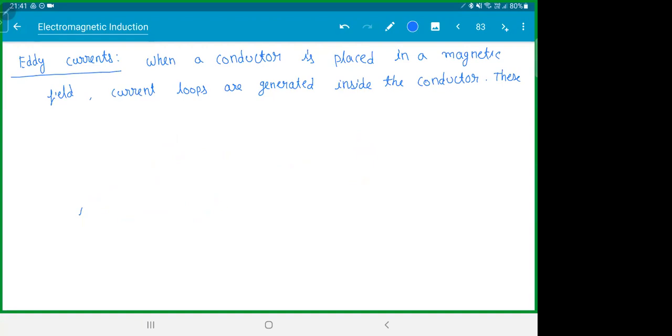In steel factories, they use something called electric furnaces. They do the same thing. They put all the metal, iron ore and everything, and they generate magnetic fields. Eddy currents are produced inside, which will generate heat, and the whole metal starts getting heated up automatically. These currents are called eddy currents. In day-to-day cases, they waste a lot of energy actually. The efficiency of the system drops because of this. You can't eliminate them, but you can decrease them a little. Let me show you how it looks. These are called eddy currents, and the heat produced is called eddy heat losses. Just a theory there.